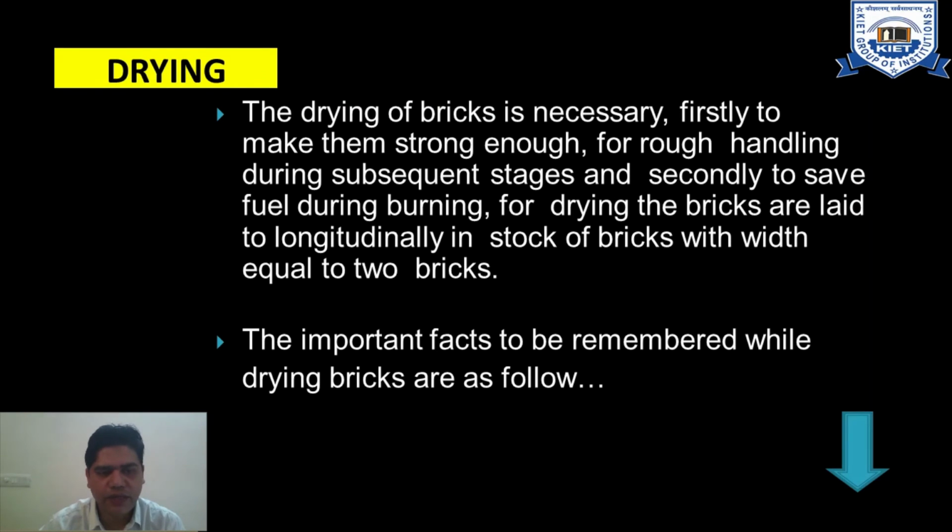Now next, after the bricks have been molded, these molded bricks will be dried. The next operation is the drying operation. The drying of bricks is necessary, firstly to make them strong enough for rough handling during subsequent stages, and secondly to save fuel during burning. For drying, the bricks are laid longitudinally in stacks with width equal to 2 bricks.